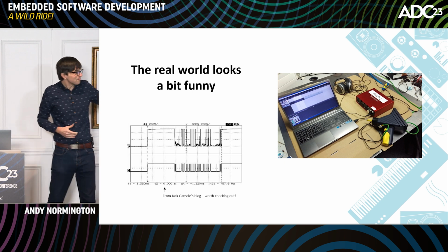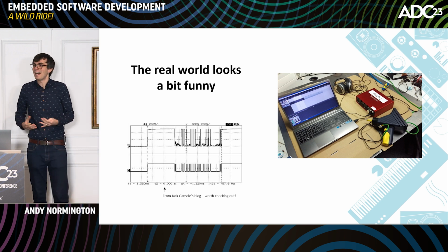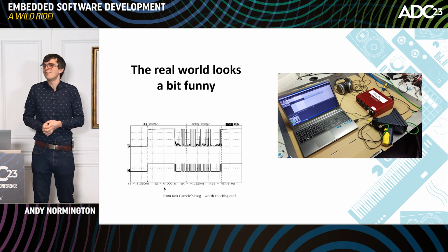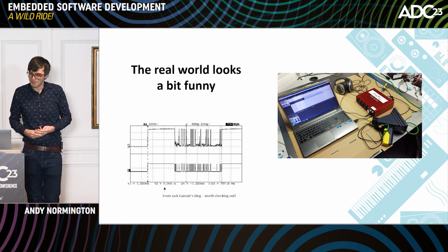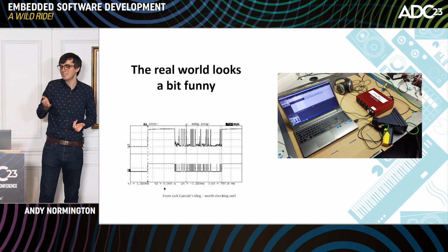We can use this ESD simulated gun. That's really fun. Zap a few kilovolts through the product, see what happens. And there's regulations that set benchmarks that we have to meet there as well of how many kilovolts we can tolerate a discharge before the customer has to get involved and do something to get the unit functioning again. Most of the mitigation for this is in hardware,